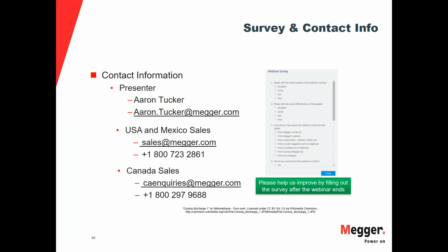It's much higher. Also, there were some other negatives in there on the deviation from phase displacement. It's just giving you the deviation from your expectation of the 30 degrees displacement, but it may be like 24 degrees or it may be 36 degrees. So that's where you're getting that negative, whether it's lagging or leading.